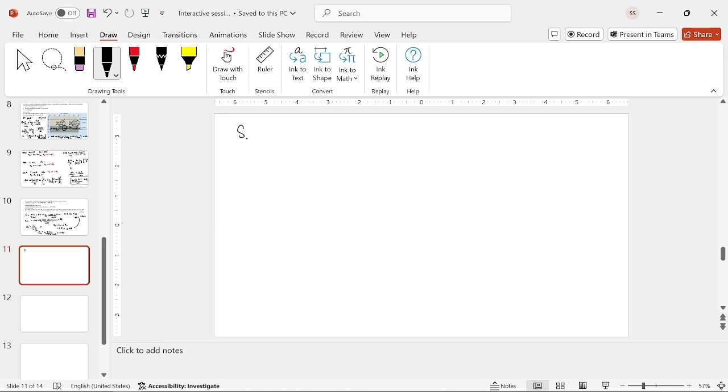So the secondary consolidation settlement will be C alpha dash H log T2 over T1, equivalent to 0.011 into 8.5 into 12 log time of secondary consolidation over time of primary consolidation. This will be 0.59 inches.